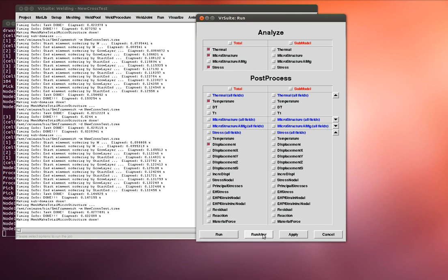We can click a run after button, which will let us set a number of seconds to wait. Sometimes this is useful if we want to run jobs overnight while we're not going to be there, and we already have our machine fully running other analysis. We know, for example, that a job is going to take 5 hours to finish. We can set our next job all up and ready to go and tell it to start after 5 hours.